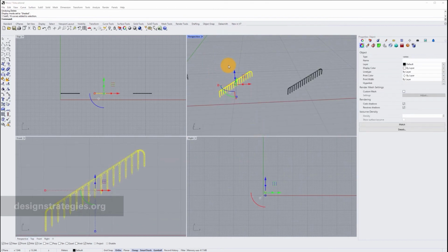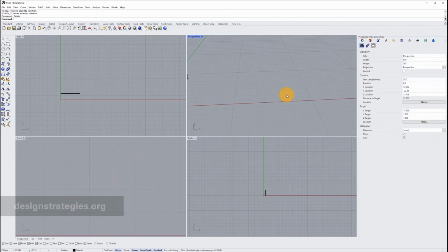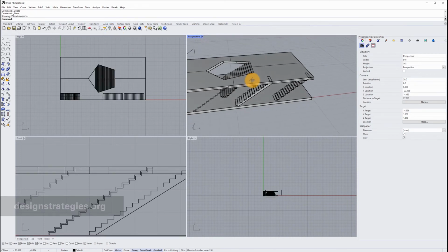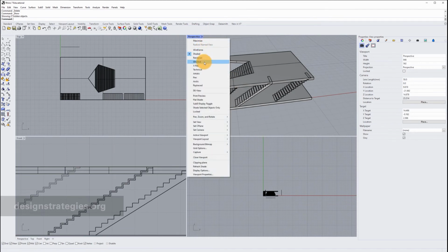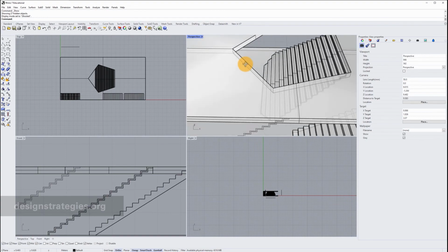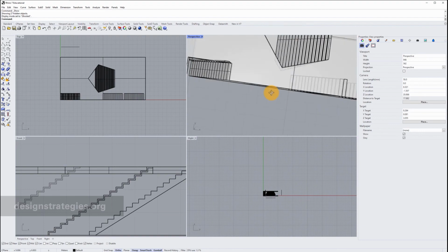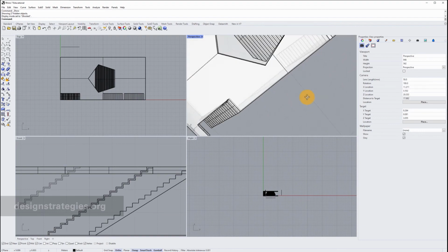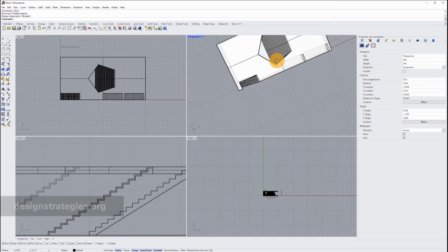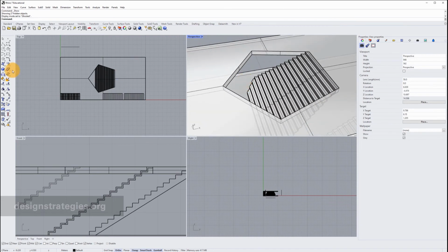We want to look at another really simple banister, a little bit like a glass banister, for example. I just delete all my elements. I show all my other objects, my scene, and I change the perspective to ghosted, because then I can see my lines a little bit better. And on this side, I would like to draw something like a glass banister. I know that there is a little bit of a kink in this area, so I have to consider this when I draw my line.